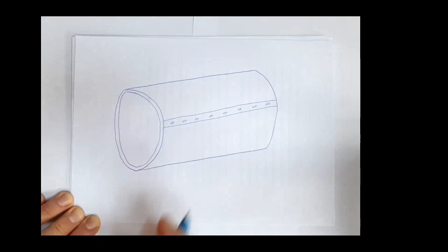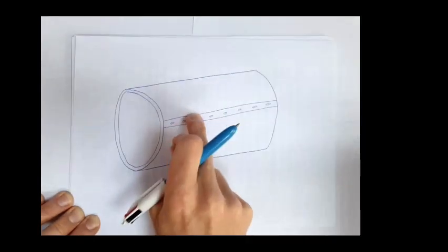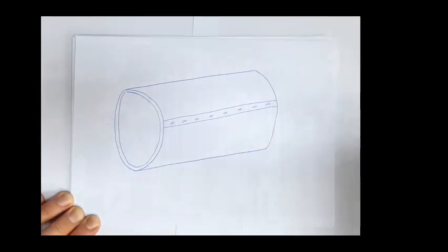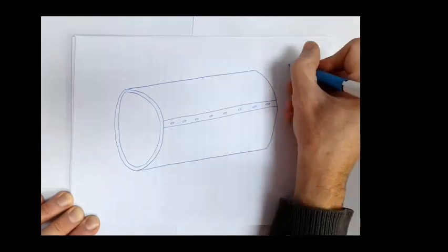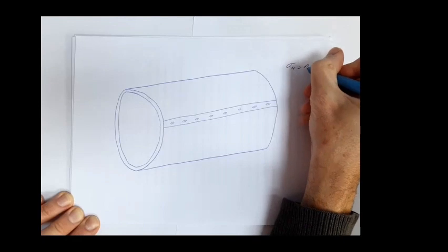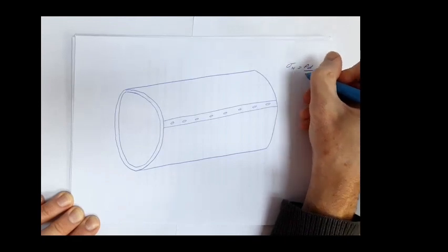So those nominal stresses are going to be influenced by how good those joints are, the efficiency of those joints, and we must take that into account. Now, how do we do that? Well, we simply take our nominal stresses and multiply them by an efficiency factor. So if we look at our cylinder, our hoop stresses are PD over 2T.